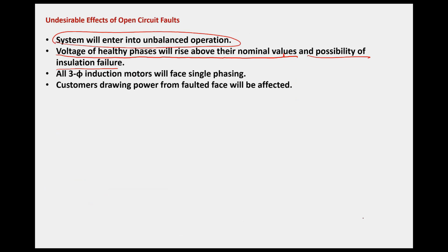Okay. Next, all three-phase induction motors require three-phase supply. 70% of the power system load is three-phase induction motors. So when one phase gets disconnected, it will enter into single-phase operation. Most of the three-phase induction motors are delta connected.